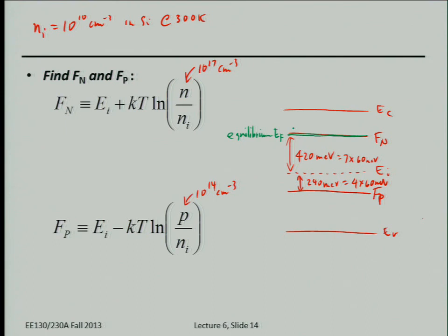So that way, when you're looking at an energy band diagram, you can tell which regions of your semiconductor device are not in equilibrium. It's the ones where the Fermi levels of electrons and holes are not the same. They're split. Okay? Yes, question.